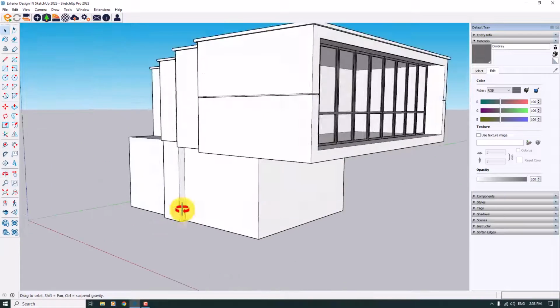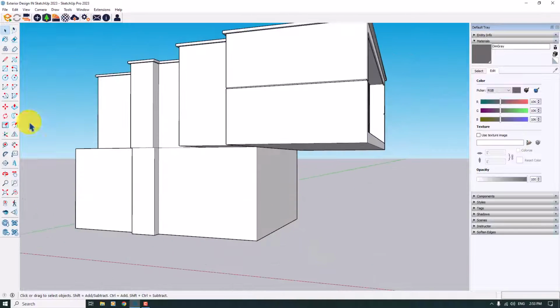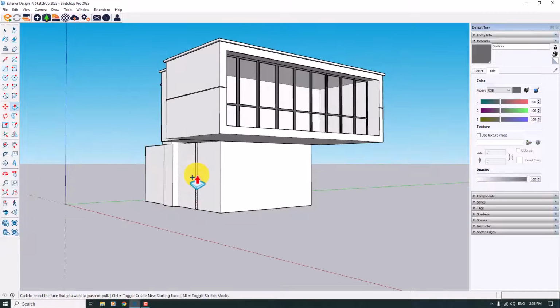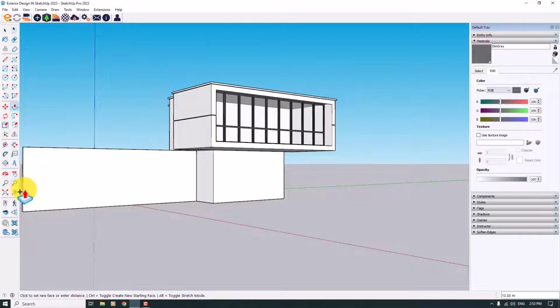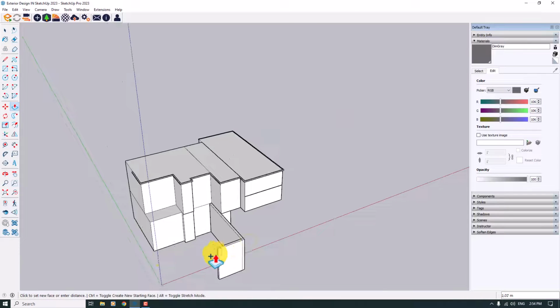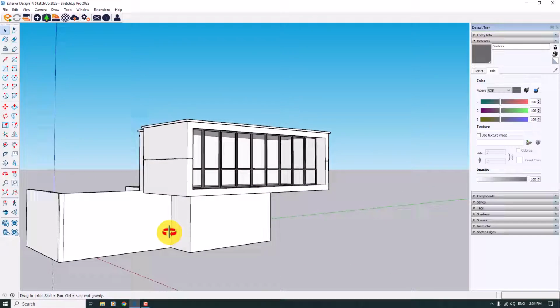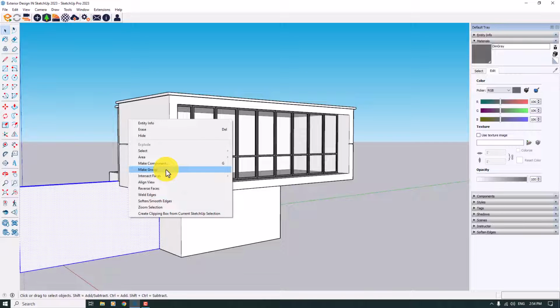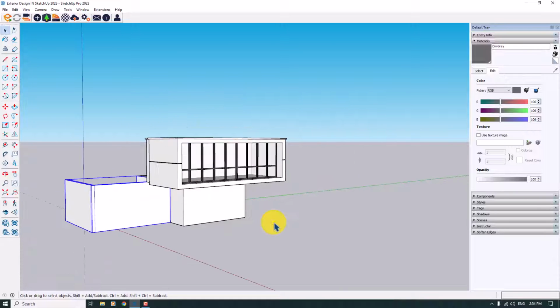So for this place I need some simple exterior wall. I will draw a wall with some dimension, for example, 0.2 by 3.4, and extrude it a little bit like this. Another extrude of about 20 centimeter, and another extrude to this part of your house. For example, this is your first wall and your second wall, related to your door and the interior part of your design. I will convert it to a group here.